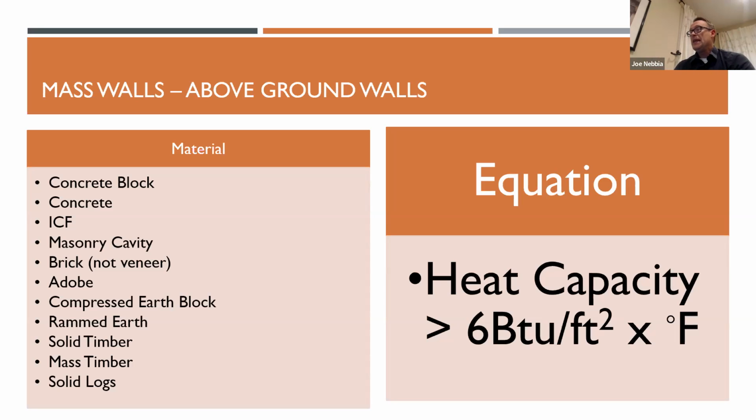So if you had an insulation manufacturer that said this should be installed without any air gaps, for example, then you could possibly be in violation of code compliance because it's not installed per the manufacturer's instructions. But that would have to be in the manufacturer's instructions.